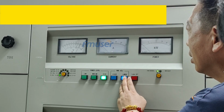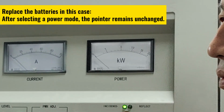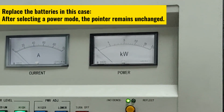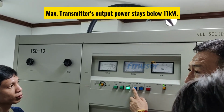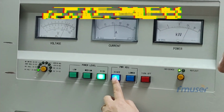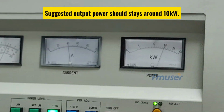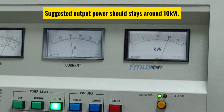If, for example, you select high power mode, but the pointer on the power monitoring screen remains unchanged, it is likely that the battery controlling the automatic adjustment to the default power is depleted, and you need to replace it. Note that even if high power mode is selected, the transmitter's transmitting power remains below 11 kW. It is recommended to fine-tune the transmitting power to approximately 10 kW to protect the transmitting system.